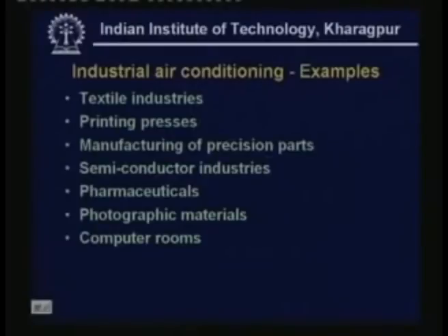And air conditioning is very much required in computer rooms, especially in large computer centers. There is a large amount of heat rejection, which has got to be taken out, so you require an air conditioning system. Also in large computer centers, there will be a lot of heat generation because of people, which also needs to be taken out. So all computer centers require good air conditioning systems. They also require clean air, because you should not have any dust particles floating around. So typically you have to maintain not only the temperature and humidity but also the cleanliness of air.